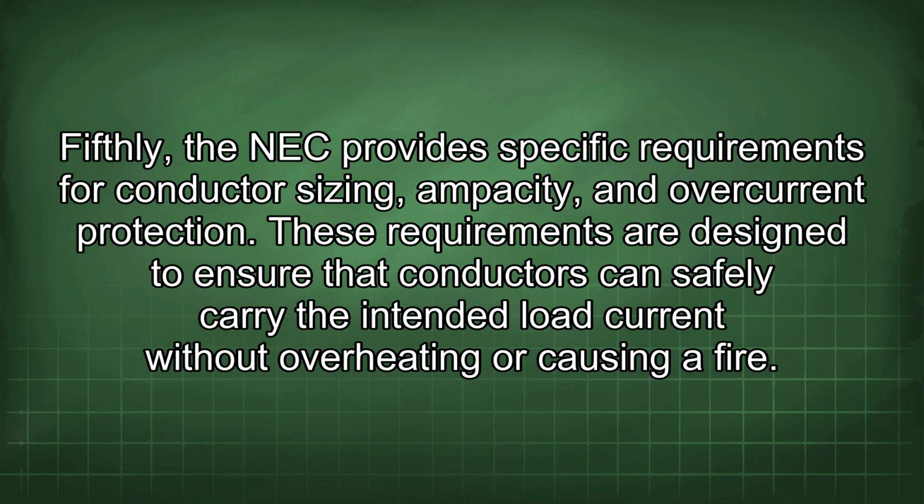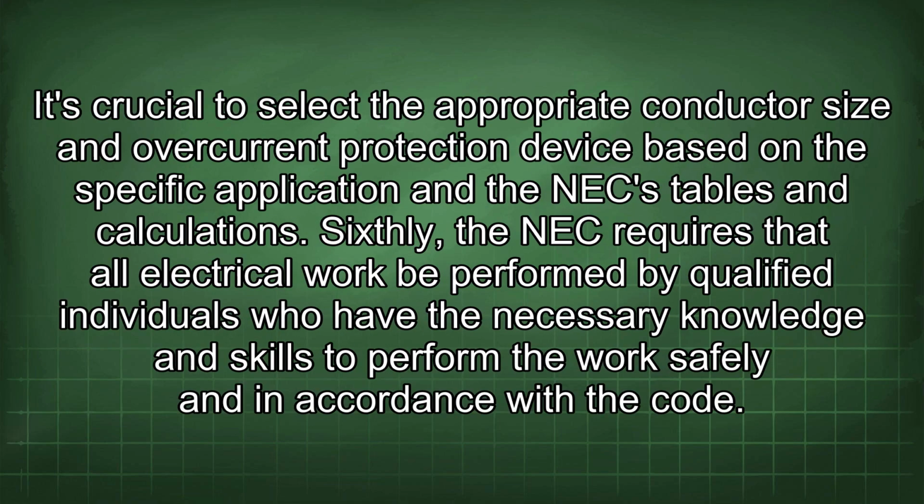Fifthly, the NEC provides specific requirements for conductor sizing, ampacity, and overcurrent protection. These requirements are designed to ensure that conductors can safely carry the intended load current without overheating or causing a fire. It's crucial to select the appropriate conductor size and overcurrent protection device based on the specific application and the NEC tables and calculations.